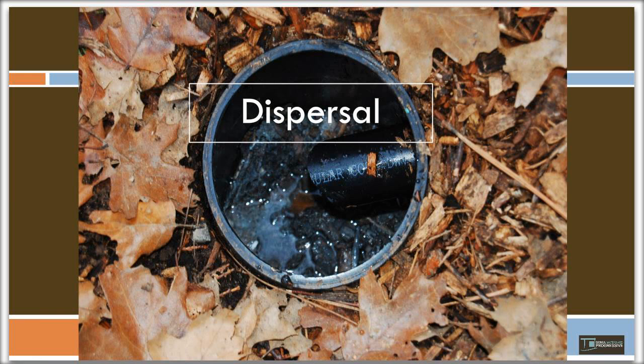And then you want to think about how you're going to disperse that to the plant. Most plants can take any kind of dispersal as long as you put the dispersal in the right place for the right plant. And the two different types of dispersal in graywater are a surge type, and that's mainly a gravity flow, and that's coming from an ABS pipe from a shower, a typical shower, or sometimes a sink installation.